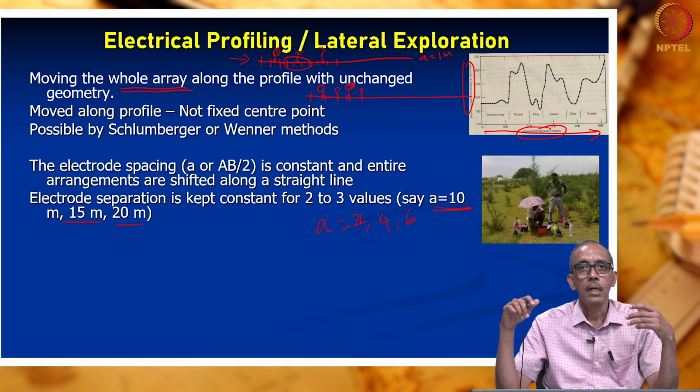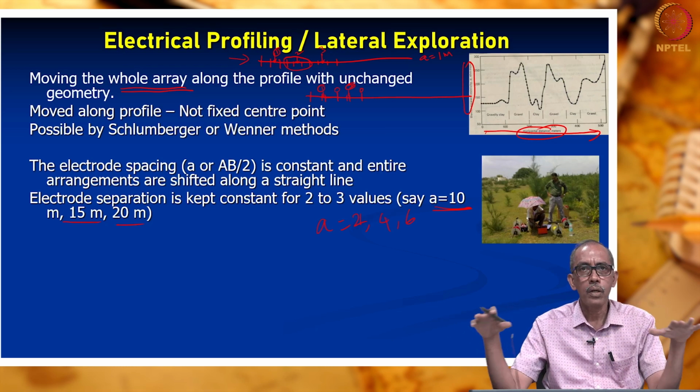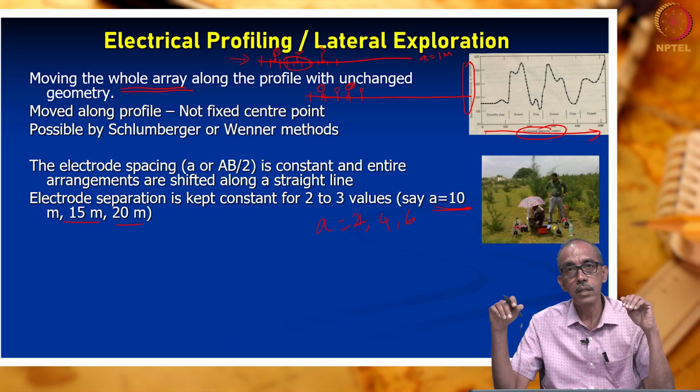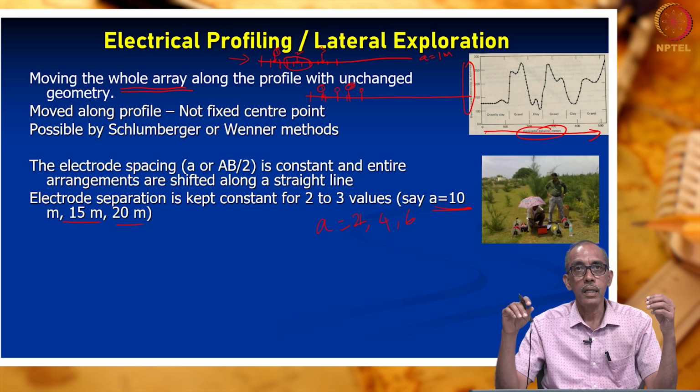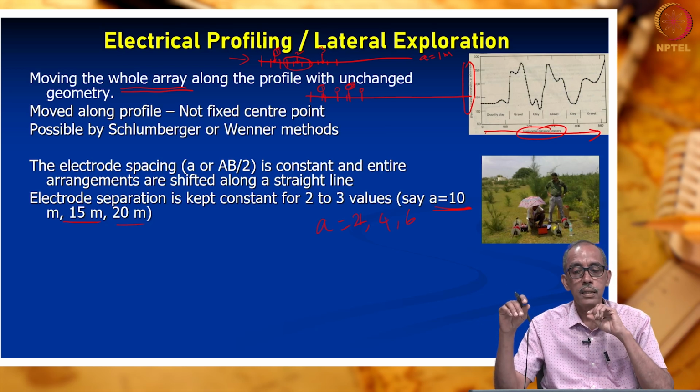As I said previously, if you are going to construct maybe a rural road, in that case, there is no need to go beyond 1 meter. Suppose you are interested in constructing a national highway, right? For that, the requirement will be much more stringent. Heavily loaded tankers, multi-axle vehicles need to pass through. In that case, the depth of investigation has to be much more, maybe 6, 7 meters or up to 10 meters if the region has got clay, right. So, it is better to carry out profiling for 2 or 3 distances, right.